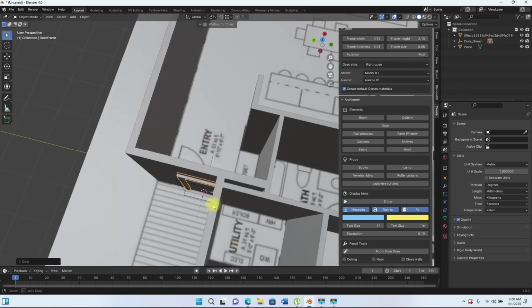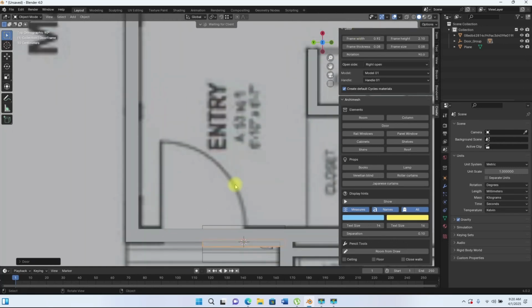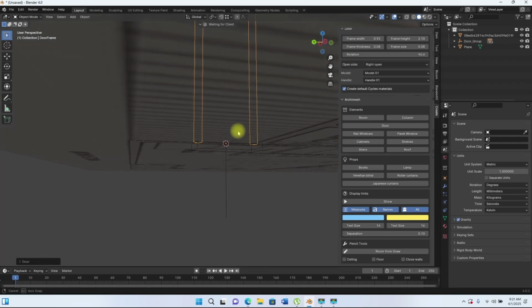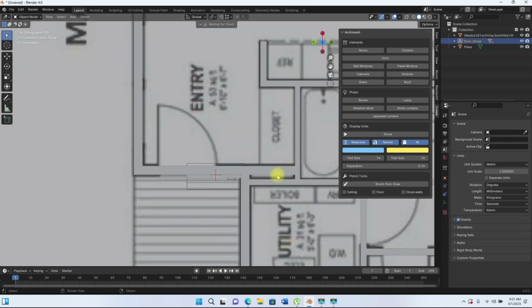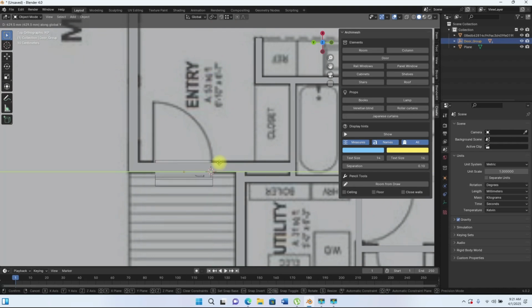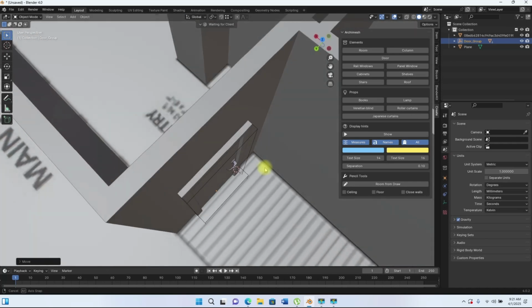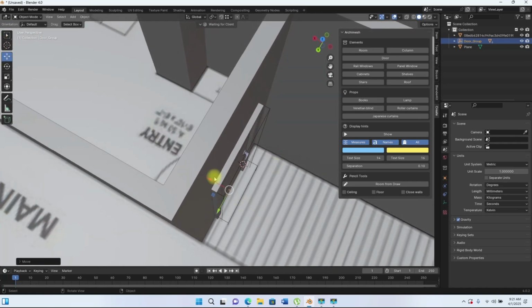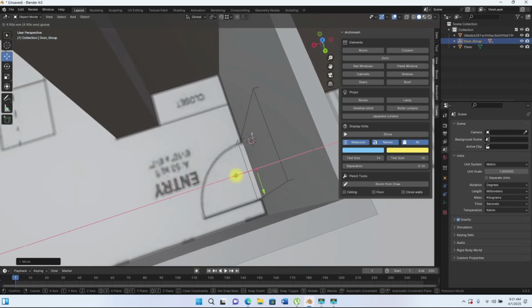So that's done. Hold down Alt to snap to this height and the top view, and then we can move this right here. So how do we move? Just select the group objects, which is this door group. Hold down Alt to move this here, and then Y to move along this. If you notice, it is actual size, all right? That's the actual size for that door. And then we can also use our move tool to move this in place so that the door can be housed inside the wall.